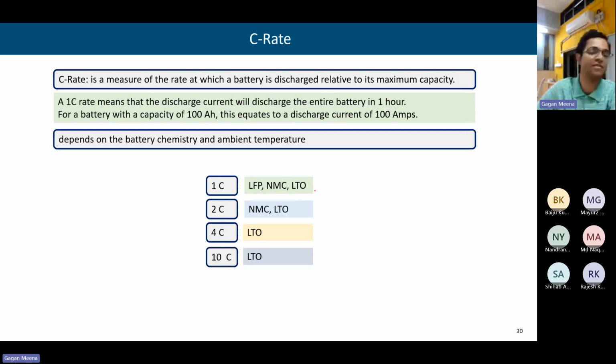These are the different chemistries for lithium ion batteries. The most popular which we use in electric vehicles right now is lithium iron phosphate, LFP. So are 1C, 2C available? 1C probably, but 2C or 3C, LTO, commercially yes. There is one company, I don't remember either in Japan or some country, that is the only country which manufactures this LTO chemistry. They have a monopoly over that.